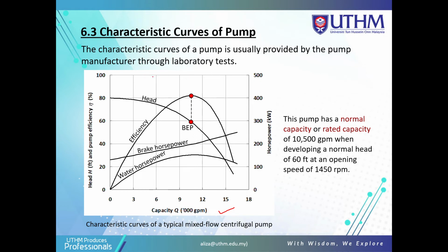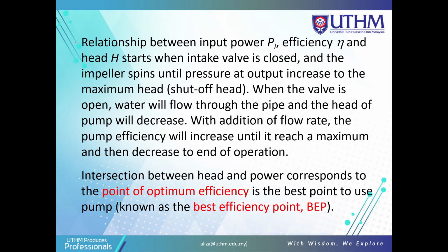Maybe the question gives you this graph, the efficiency, the head, the BEP and so on. Explain based on this figure. You just baca je lah, and explain what the power input, the efficiency, and the head are.